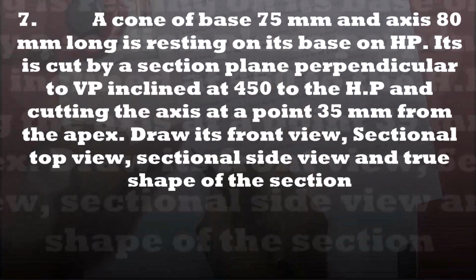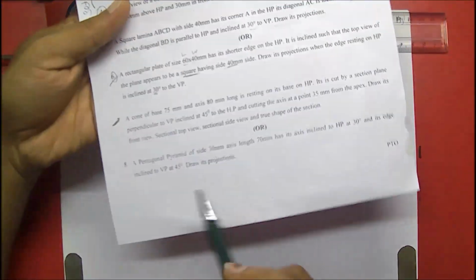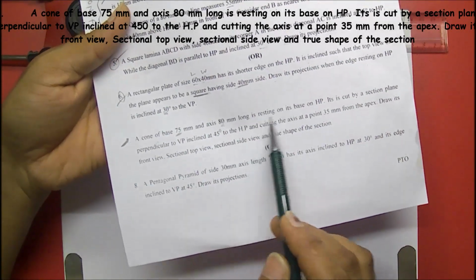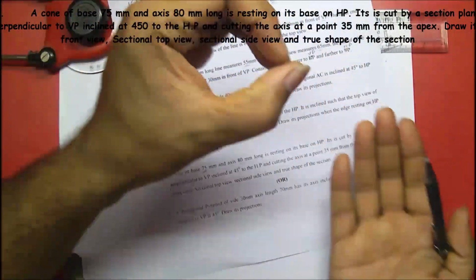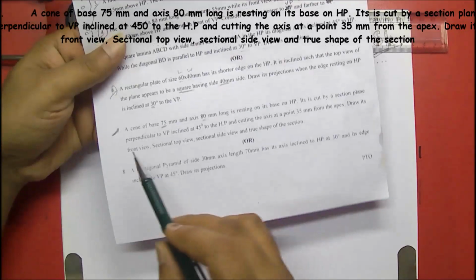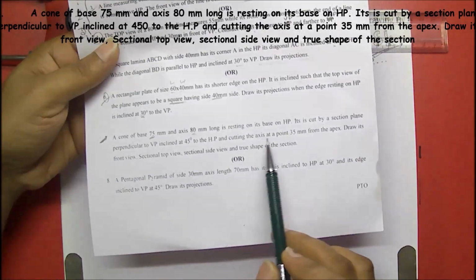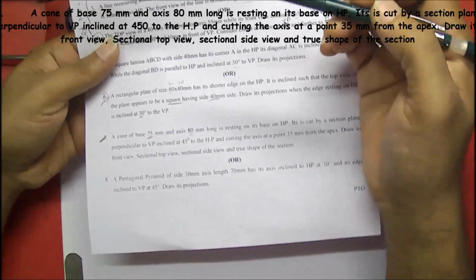Now we are going to discuss question number 7. Let me read out the question here. The cone of base diameter 75, axis 80 long, is resting on the HP with the base. Means this is the cone, resting on the HP with the base. It is cut by a section plane perpendicular to the VP and inclined at 45 degrees to the HP, means auxiliary inclined section plane, cutting the axis at a point 35 mm from the apex, means from the top of the apex.